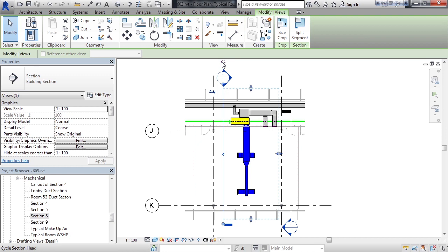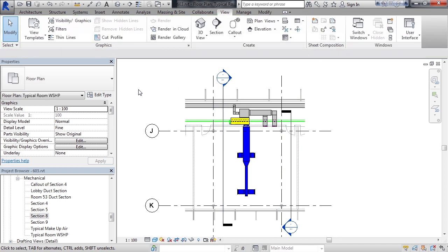If the orientation of the section is not in the correct angle, you can use the rotation icons to rotate the actual section. Note that the section symbol does not have anything in it right now. That text will be filled out when you place the section on a sheet. Once you're done at this point, simply click away from the section and that section mark is created.